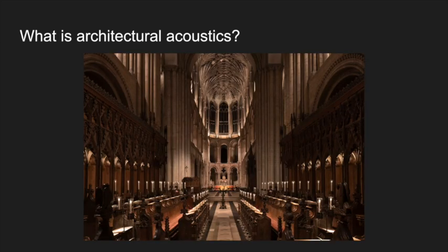Some important acoustics terminology and descriptors can define how a space sounds. So, a space that has significant reflective material or is reverberant is live, and contrarily, a space that has significant absorptive material and low reverberation is dead. As an example, a cathedral could be described as having a live sound due to its echoic properties, since it has lots of reflective materials in it, like stone, glass, concrete, some wood, marble, things like that.